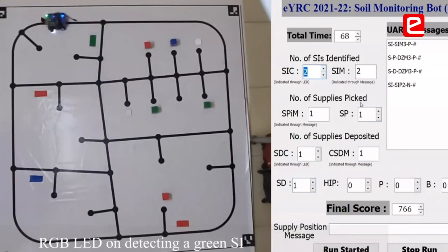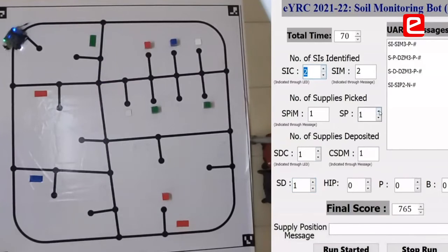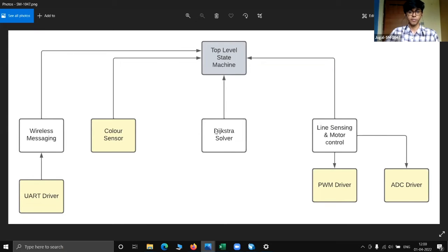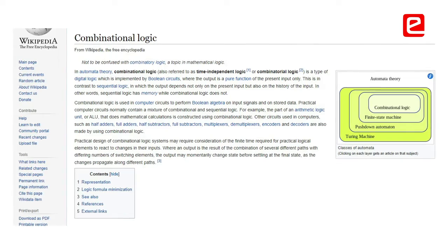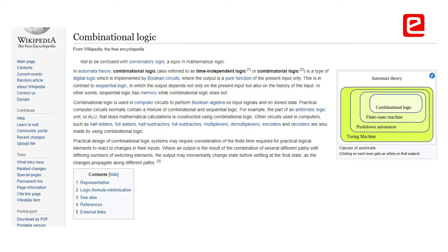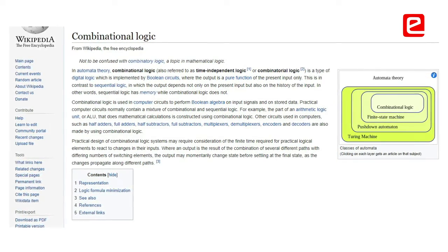I made a bank of comparators that took in 26 different numbers, and almost instantly outputted the minimum path among all those numbers and the index of that path, so that it can be used by the state machine. So basically, it used combinational logic instead of sequential to shave off a major chunk of execution time.